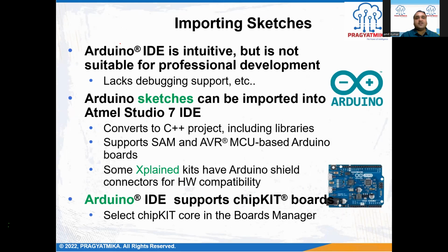So Arduino sketches can be imported directly into Atmel Studio and the Microchip environment. It converts the C++ project. The Microchip XC compilers support both C and C++ languages. And there is one more thing. Microchip has chipKIT boards directly from Microchip if we are purchasing. So there are the Arduino boards, and then there are the chipKIT boards. The chipKIT boards can also work directly with the Arduino IDE.